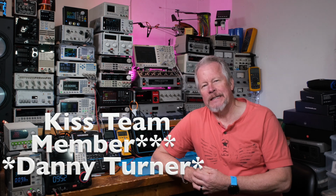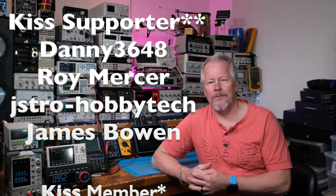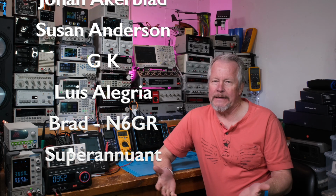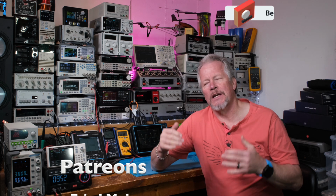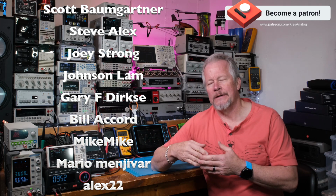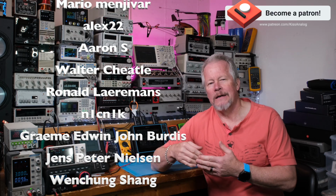All right, guys, so what do you think? Looks pretty cool, right? So that's just another way to review your design before you send it off. The Gerber files are what you send off to the board house for them to make your boards. So I hope that was interesting to you. If you haven't seen before, there are lots of free Gerber viewers. But now with KiCad, you get one built in. There are also lots of board houses where you can upload your Gerber files and look at each layer. So there are a lot of viewers out there that are free.